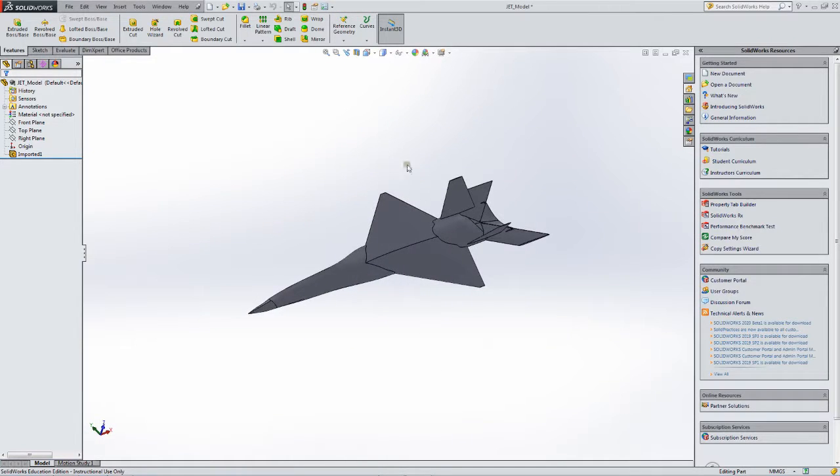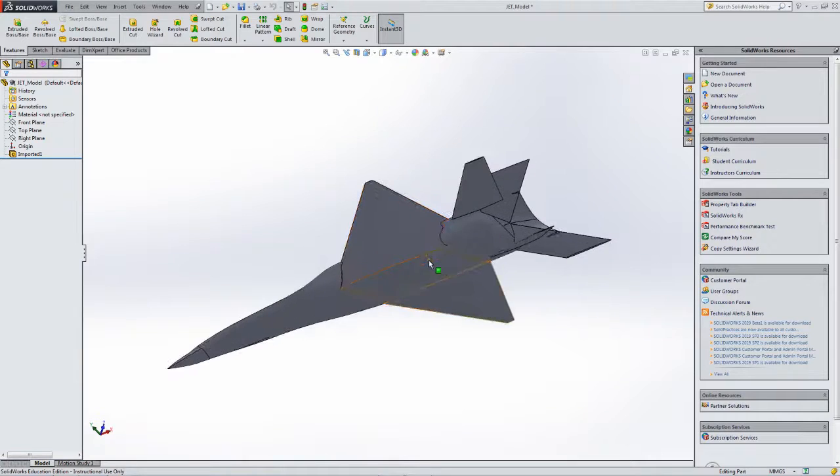It's useful, especially when we take this CAD geometry and do CFD or something like that with it. It's good to have the x-axis run down the longitudinal axis of the airplane and the y-axis run out the right wing. Now, a little bit about CAD.